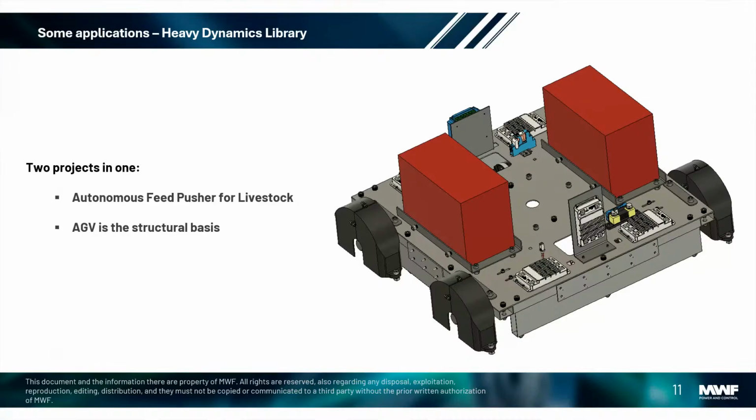During the design of this platform, we had to define accurately the amount of power which would be needed to drive the wheels, and to analyze the trafficability as well, by checking if the lateral slippage was too high or not, and if the control system would work even in the presence of many uncertainties, like the position of the center of mass, backlashes, and many other uncertainties that we know that we are going to have once the mechanical system is finally realized.